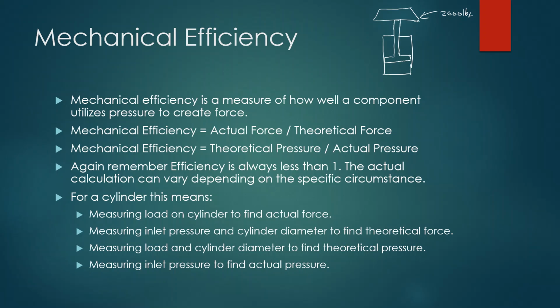And let's say this has an area right here. Actually, here. Area, we'll say this is equal to 2 inches squared. So you're like, okay, well, what's the pressure required? Well, if you do 2,000 pounds force divided by 2 inches squared, you're like, oh, well, I can do that. That's 1,000 pounds per inch squared, right?